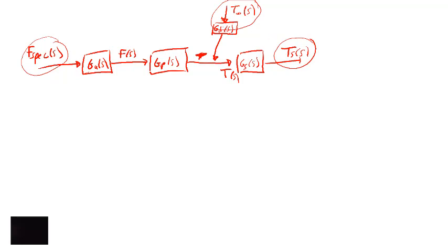Okay, so we can group things together, and to do this I'm going to call this term A in the Laplace domain, and I'll call this B in the Laplace domain, and these two add together at this point to affect T. I'm just going to do this for simplicity. So essentially we know that T in the Laplace domain equals A plus B. We also know that this term G of S, what we really care about, is this term coming out over here.